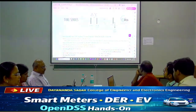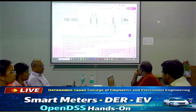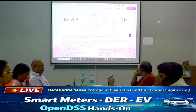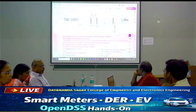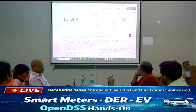Here you mention only the values, and these are all in PU, per unit. Okay, so this will get multiplied, it is on a base of 1, right? So you mention per unit values here. This is how we define a shape. Then in the load, whatever we had done before, we have created a load of 1000 kilowatts, where you mention this profile, the daily profile, you say this.